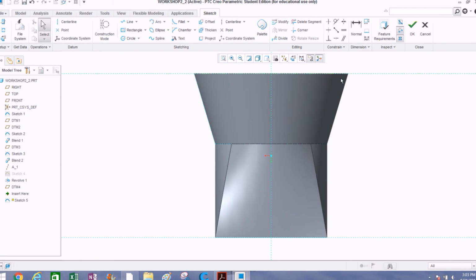So what we're going to do, and you can do this in any way you like, but we're going to go ahead and choose the spline tool right here. Click it once. We're going to want to grab this up top left corner, click once, drag over, approximately halfway through. This isn't exact since I didn't dimension this for you. Click again, and click one more time, but we're going to do that on this bottom edge now. So click one more time, and come off and center click.